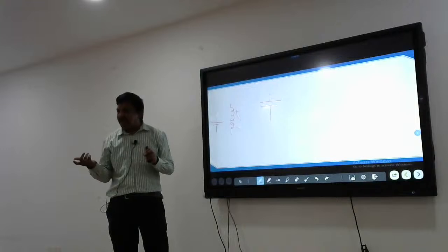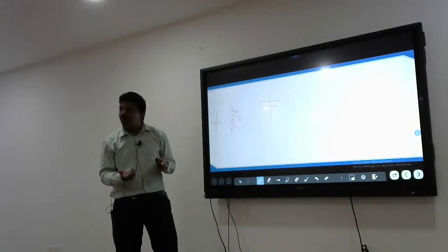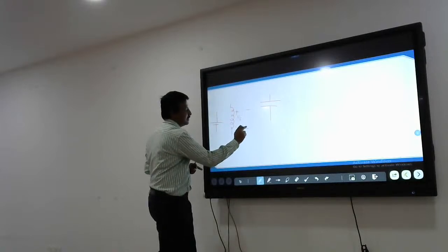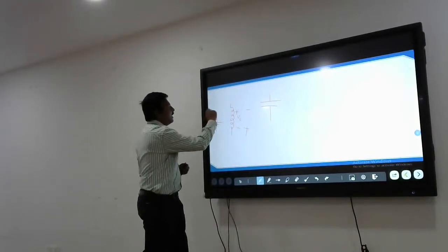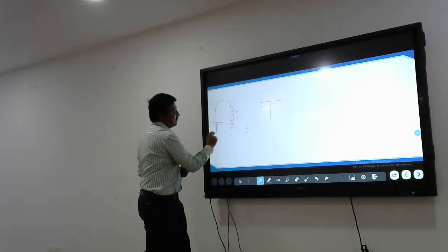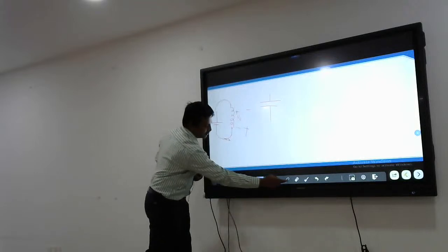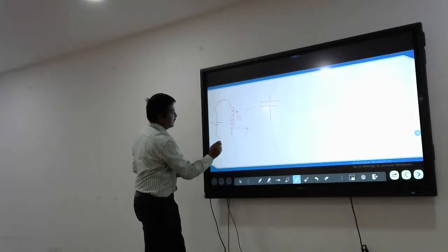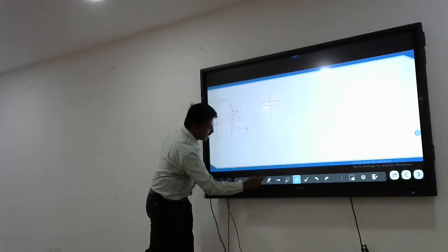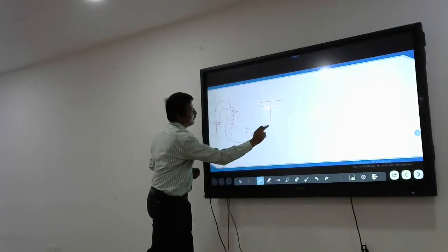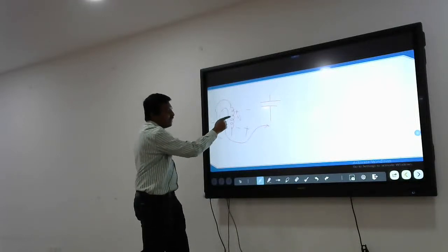The beauty of the inductor is, for example, when you make it discharge, the current decreases and the voltage changes polarity, from minus-plus to plus-minus. Previously you connected like this, now you are connecting like this. When the voltage changes polarity, you allow the discharge to the load like this. That means VDC and VL are adding.